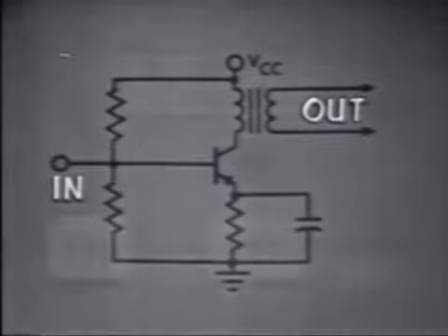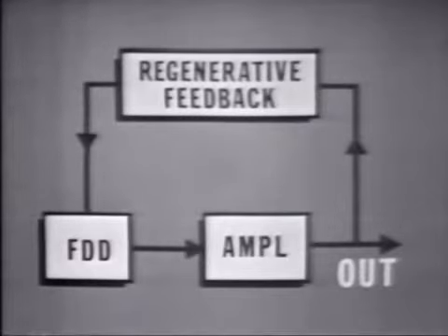And thus we see the need for a frequency determining device. In this case, the LC combination. These component values are carefully calculated to oscillate at exactly the right frequency. Then the exact amount of feedback, and we have an LC oscillator that provides a signal of constant frequency and amplitude.